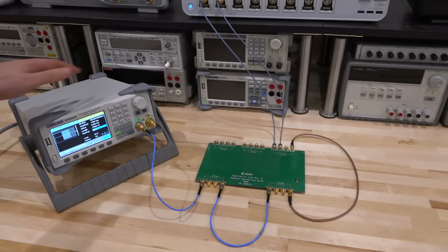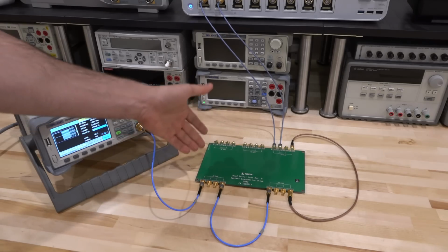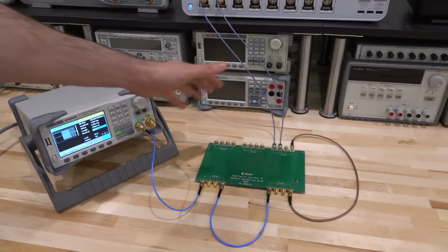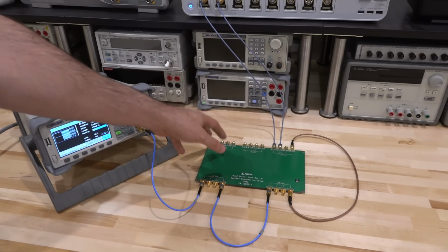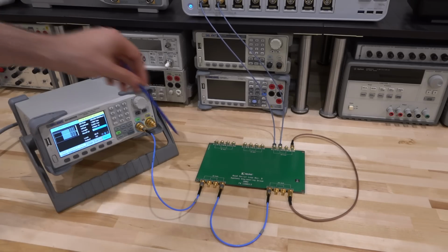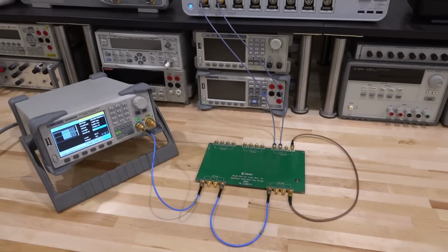Here I have the output of the source directly connected to this serial loopback board, and the way this board works is that it has a number of traces built into it, and it's intended to be used for ISI and crosstalk investigation. So I have put multiple traces in a row. I have a 30-inch trace, 20-inch trace, and 40-inch trace all serially combined with each other. So we're looking at 90 inches of PCB trace at the same time.